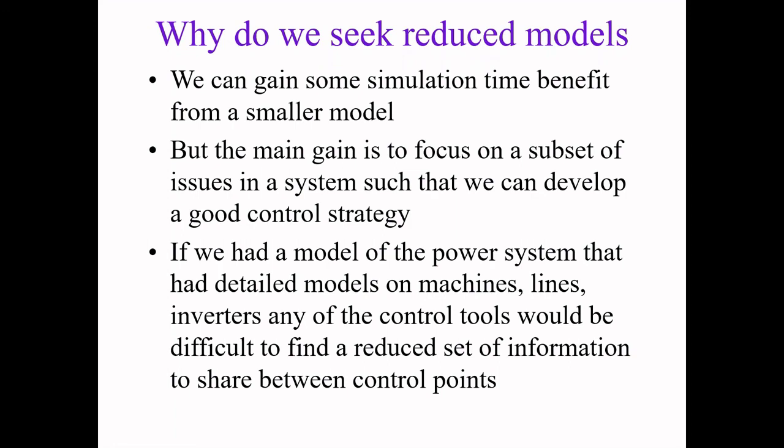But one of the main goals to focus on a simple network, a simple representation, is that we can develop a good control strategy. If we had a model of the power system that had detailed models of every machine, every line, every inverter, any of the control tools that are currently available would find it difficult to say, well, what information is important? How can I come up with a control design when I've got this 5,000th order model to try to represent my system?